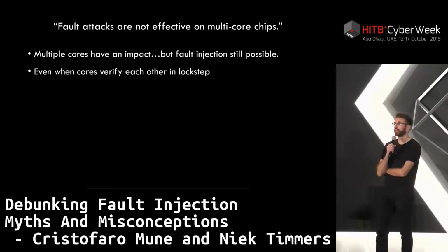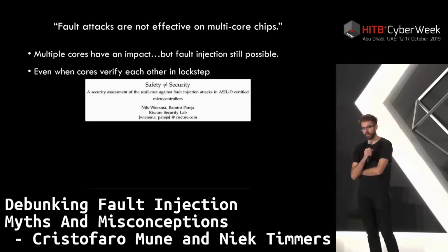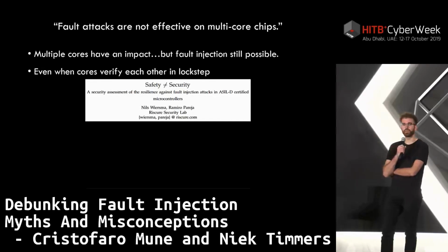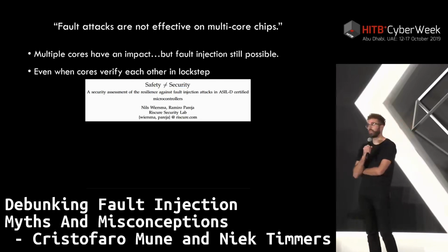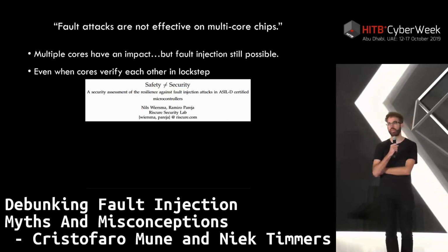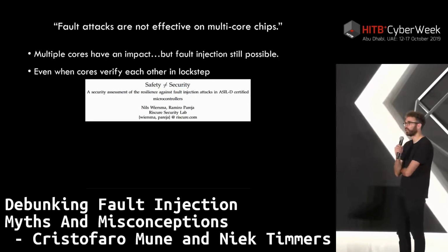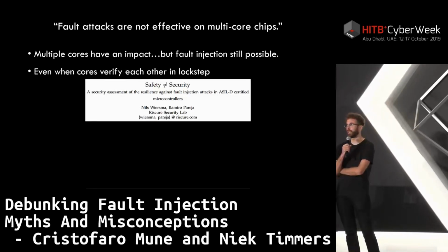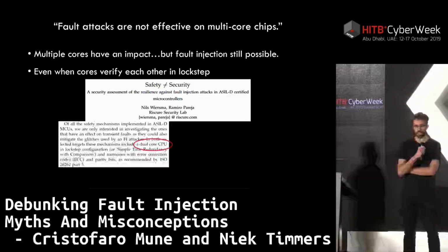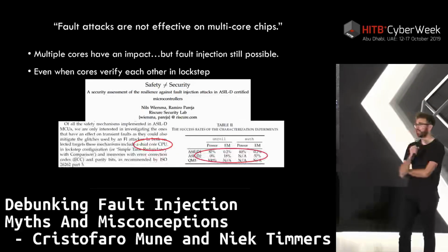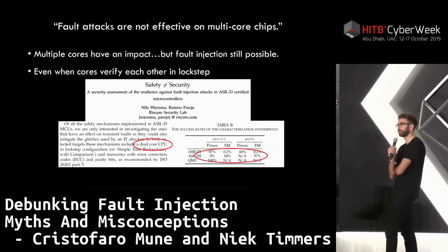And that's exactly what we are trying to exploit, using fault injection to make sure that this software is executed incorrectly. The paper where this was described is called Safety is Not Security, and it already hints at the fact that this lockstep mechanism in the automotive industry is not designed and implemented for security, but for safety. Because, for example, if you have a very important controller for the steering of your car, you want to make sure that this software gets executed correctly, because otherwise your car might steer in the wrong direction. But they've shown that on dual-core versions of these lockstep chips, it is possible with a very high success rate to actually inject glitches within this system.